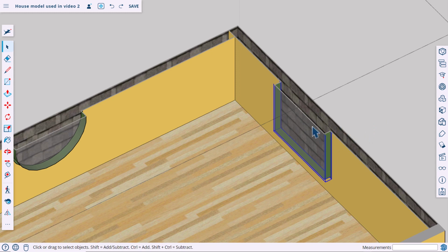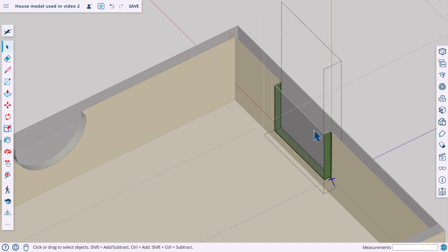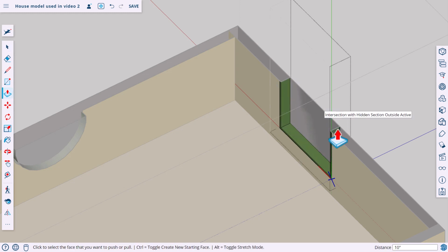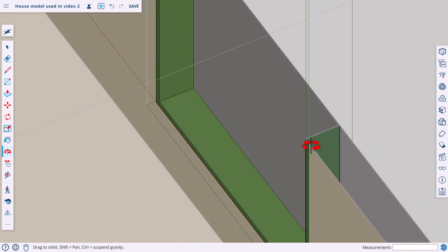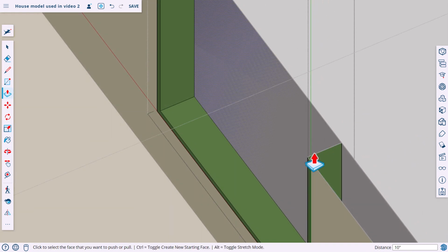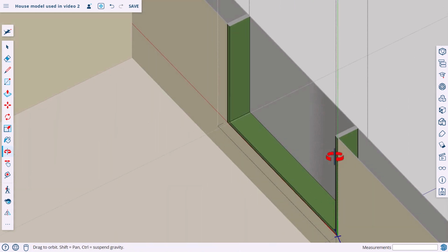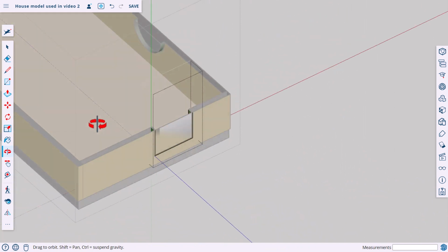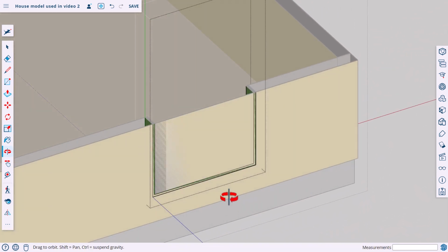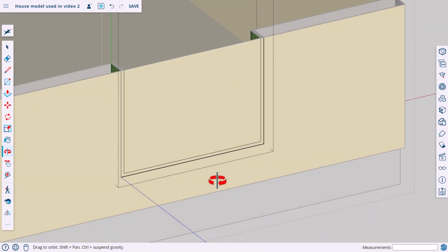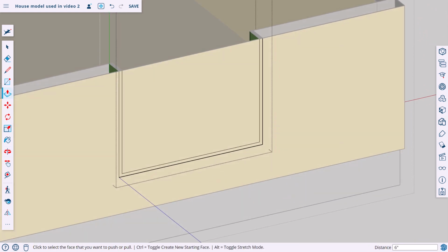It actually distorts the wall just because of the way that the window was created. So instead, what I can do, I'll just edit the window and I'll push-pull the window out to the outer surface of the building. And in fact, maybe I'll push-pull the frame as well. In this case, I'll tap Control so that I get a copy on the outside of the building. And if you think about it, that's actually the way that the frame should look. And now when we spin around to the outside of the building, you will see that familiar Z-fighting. I have two surfaces on top of each other.